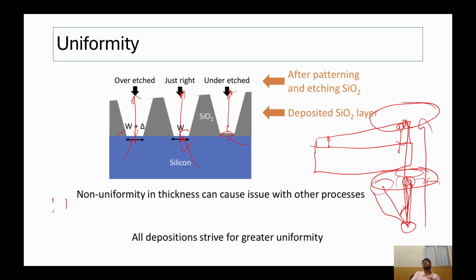If you are going with sputtering, you won't get anything at larger distances, but in the case of physical vapor deposition like e-beam evaporation or thermal evaporation, you will get more uniformity at larger distances.